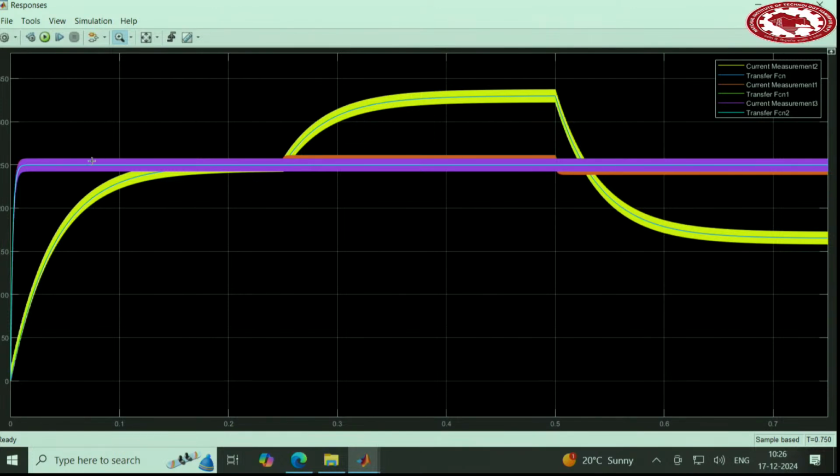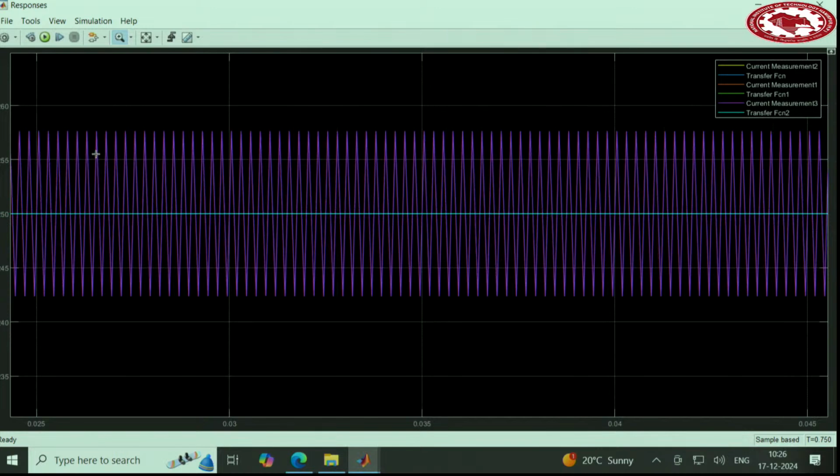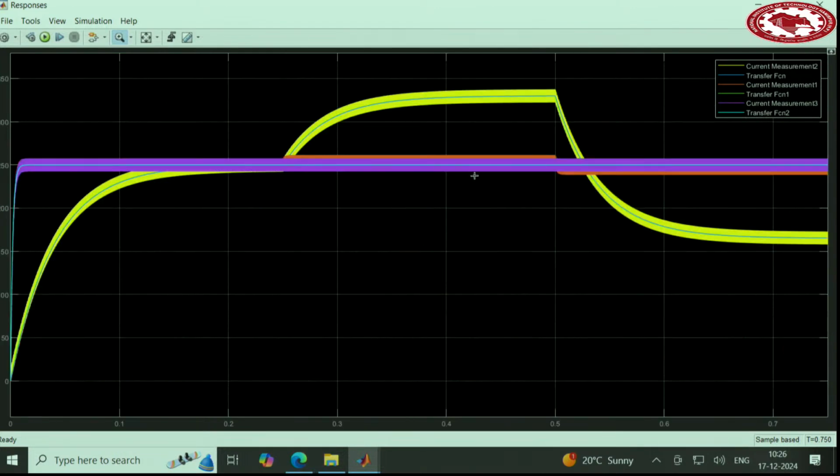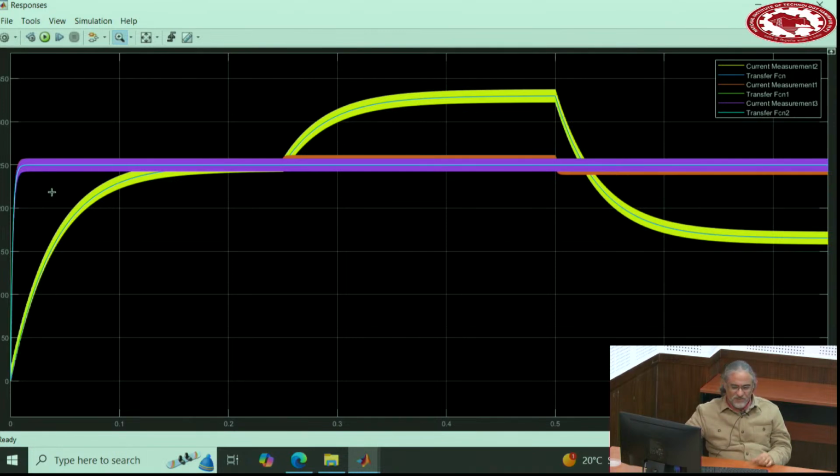All right, and this one, the pink one, is when you also use feedback linearization, input feedback linearization. If you look at the response, it's not sensitive to anything. Only maybe a little bit to the resistor, but with resistor we didn't check here. But it's not sensitive to VA, it's not sensitive to VB, it just exactly runs at 250 amperes, no problem. Even virtual resistance is needed in input linearization. If you don't put it, your circuit will be sensitive to resistance, because feedback linearization fixes VA and VB, but not R. So it's good to put it there.